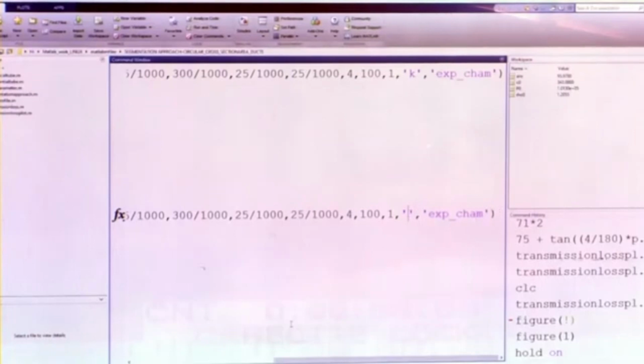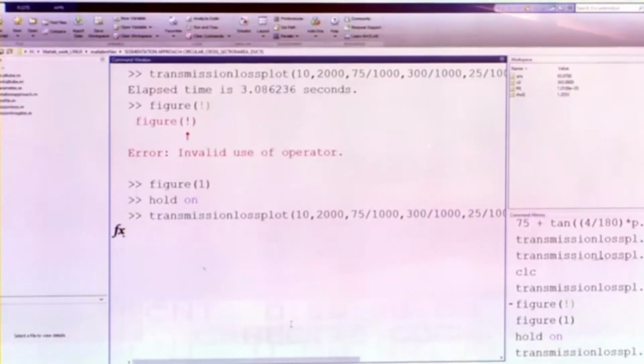plot it with a different color, but a larger number of segments, 200, double of the last one. So, the conical duct is divided into exactly double the number of segments. So, the graphs are nearly identical. I can just remove this part, and they are identical. I mean, if we do it for 400, 800, we will see the results have converged, and it will match exactly the analytical solution, although we are not comparing it right now.